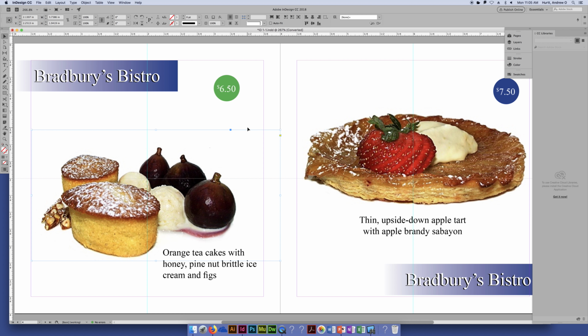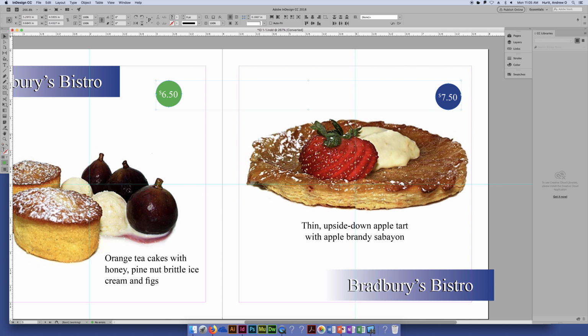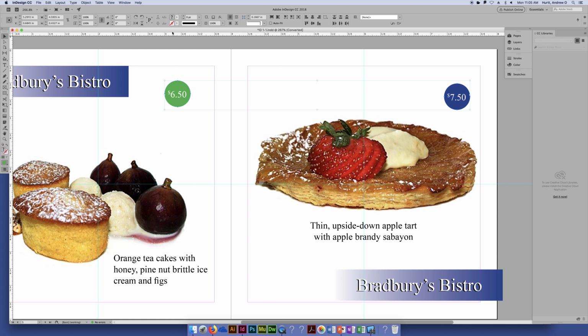You can also align objects when you have, I'm just going to grab the circles here, which are actually not aligned. So you can align your objects, and in the same way, if you want to align this green circle to the blue circle, you have both these objects selected, and you click the one you want to align to one more time, and you see you get this highlight. And let's align centers. Now I didn't select this on purpose. And now we have our two circles aligned. It aligns the green circle to the blue circle.